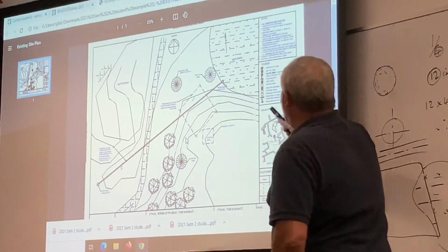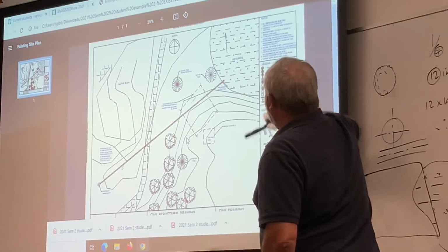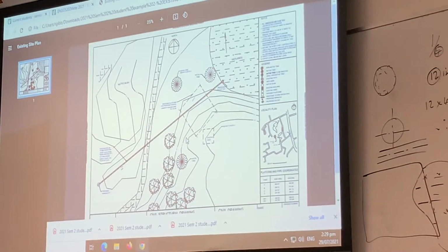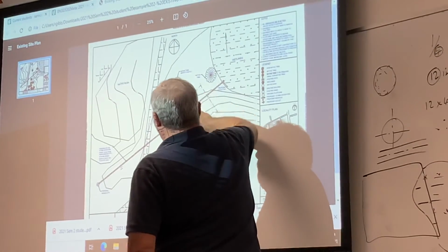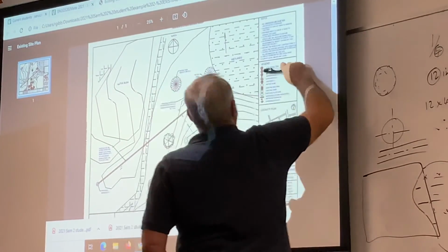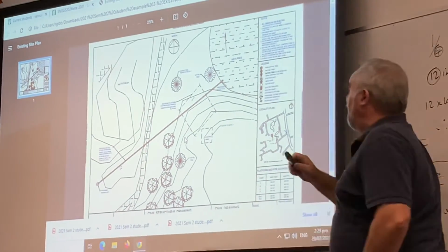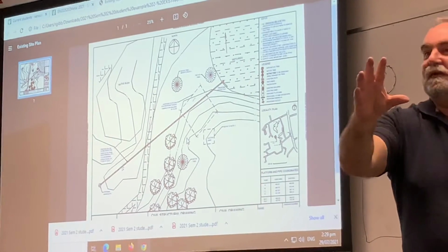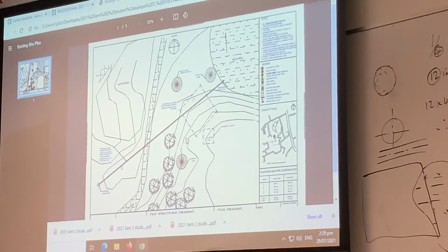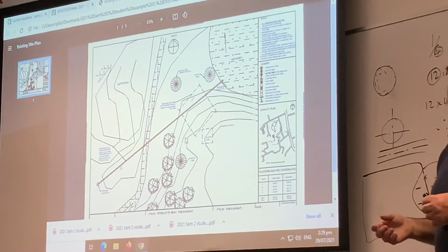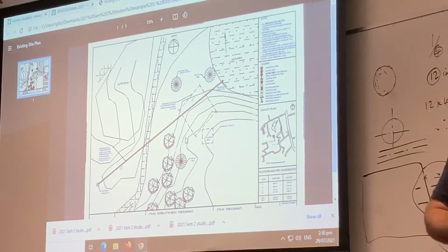Everything's pretty good there. This is a little bit marginal because it's printed with a big blur, and I'm trying to see which one of those, which look very similar, is what, and I've got two big blobs there. You see, the problem with AutoCAD is you can zoom in on it and it looks perfect. But you've got to be thinking of what's coming out the other end. If you're not sure, do a print. Print to a PDF and have a look at the PDF. Or print to an A1 print. Take it away and have a look.